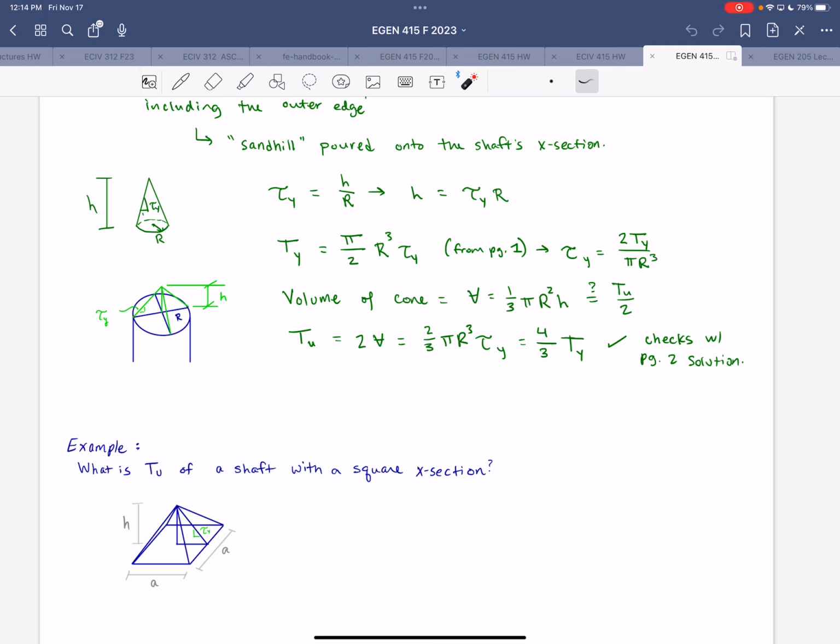There would be no out of plane stress due to pressure. Yeah, you would. That's just an assumption we can make with thin wall pressure vessels. Yeah, that would be one of the principal stresses, and it would be a value of zero. It's close enough. It's not going to be perfectly zero because of the pressure differential between the two sides, but it's close enough to zero compared to the other stresses that we can approximate it as zero for the purposes of this class.